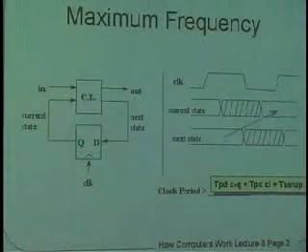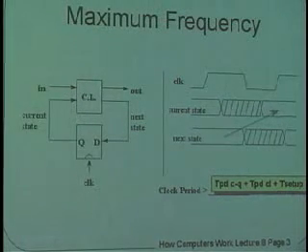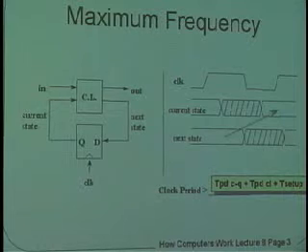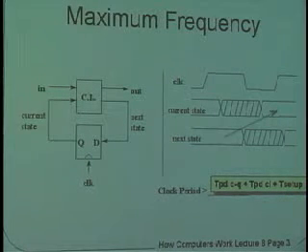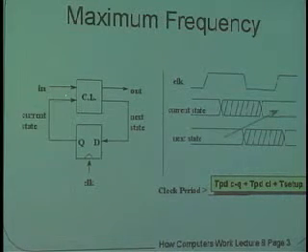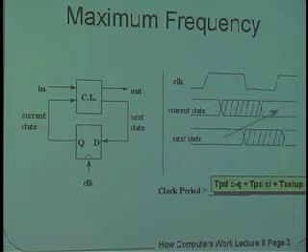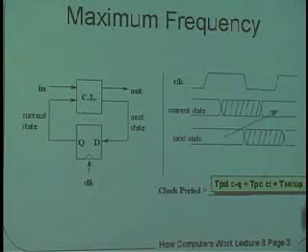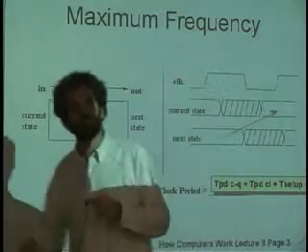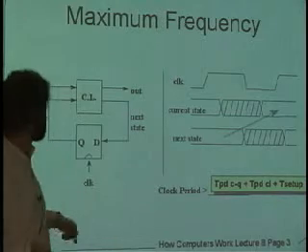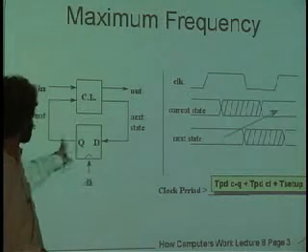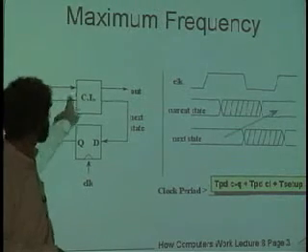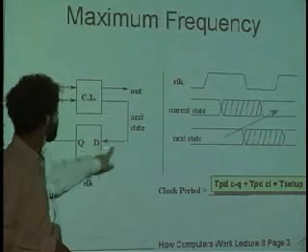Okay. The second constraint that we had with regard to timing was when we could click the shutter the next time, which is a question of when the new data about the next state comes around through the combinational logic in order to get back to D. And if you remember, there we were talking about the propagation delays, or what's sometimes called the maximum propagation times, between the clock and the Q. And after that time has passed, there's some propagation time from here to here, then back around.